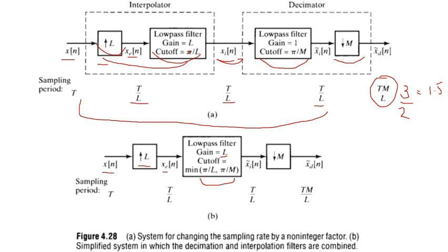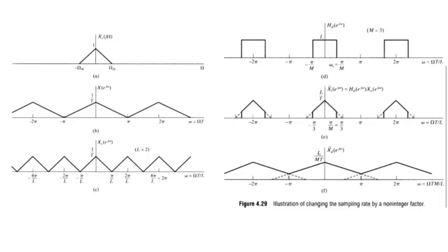So let's move on to the next slide and have a look at the overall sampling process with upsampling and downsampling. Here is the spectrum of the original signal. Here is its discrete time Fourier transform, the sampled version. You can see here the copies are almost not aliasing but just too close.